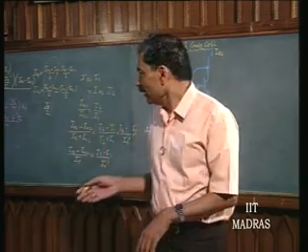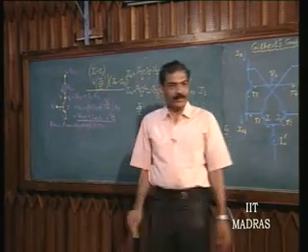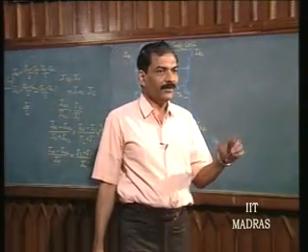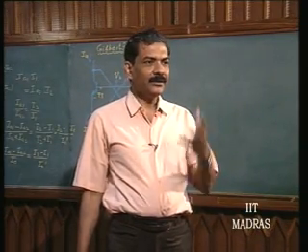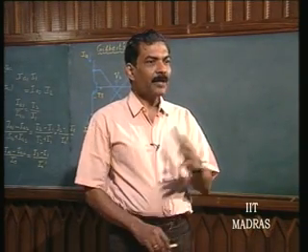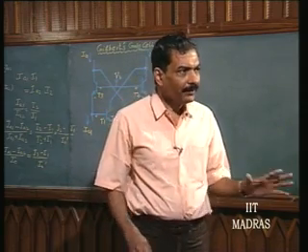So, I can see to it that this ratio of current is going to be same as ratio of areas, which means it is just geometry dependent. That means absolutely constant, independent of temperature, supply voltage, everything.